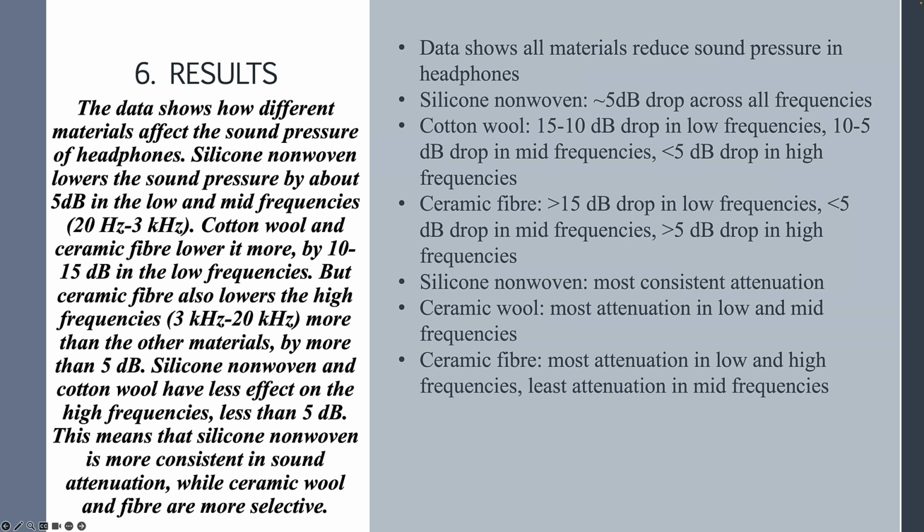At high frequencies, 3 kHz to 20 kHz, the sound pressure drop is smaller than at low frequencies. In the case of silicone non-woven and cotton wool, these values are below 5 dB, but ceramic fiber causes a noticeably greater drop, exceeding 5 dB.